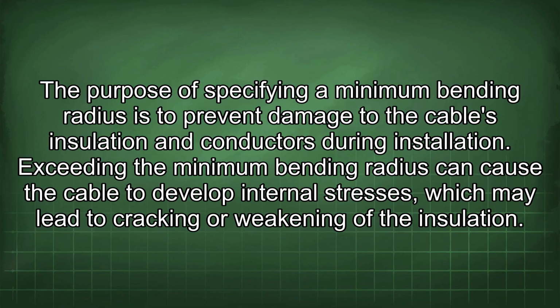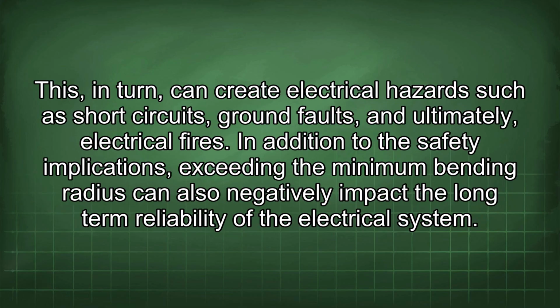Exceeding the minimum bending radius can cause the cable to develop internal stresses, which may lead to cracking or weakening of the insulation. This, in turn, can create electrical hazards such as short circuits, ground faults, and ultimately, electrical fires.